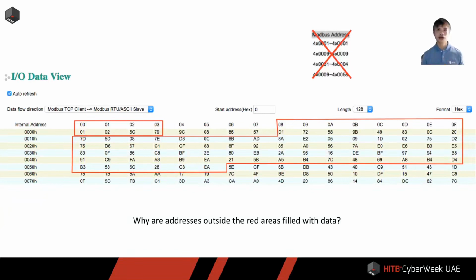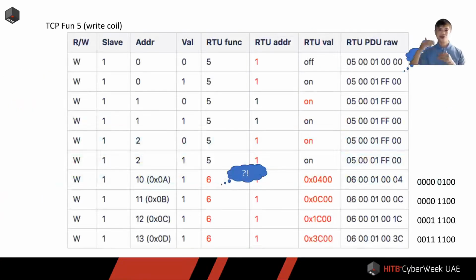I'm quite confused by 4x, because according to the manual, 4x01 means the internal address starts from 1, and 0x something means the internal address starts from 0. So you might think 4x01 equals 0x00, right? But actually, no, we don't really know what 4x stands for here. So we decided to just input the data one after another and see what's going on.